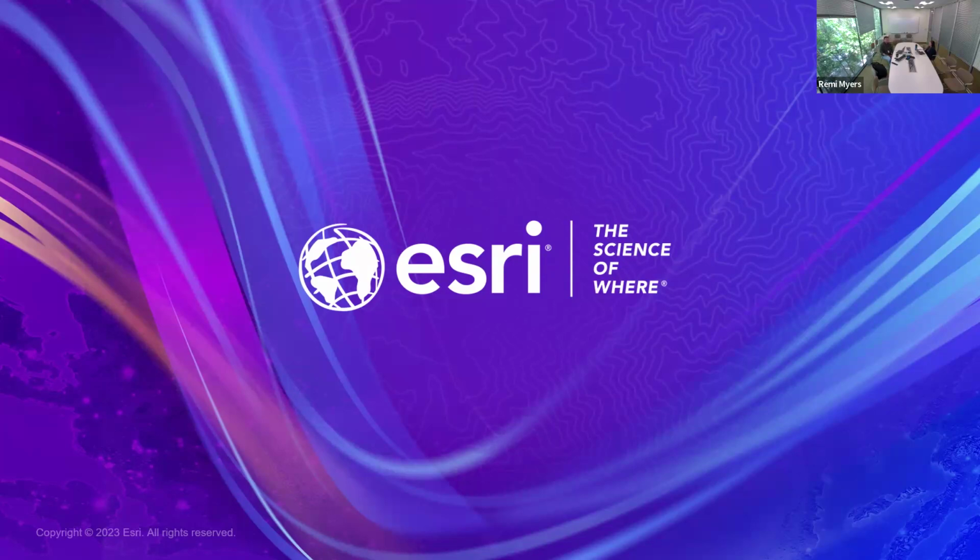So the team has created a new GP tool, prune. I was about to say trim, it's called prune. What prune will do is, when you have some of these excessive records that are not necessary, you can run this prune tool, and it's kind of like the old compress in traditional versioning. You don't have to run it every day, but it is there to reduce some of the database bloat.